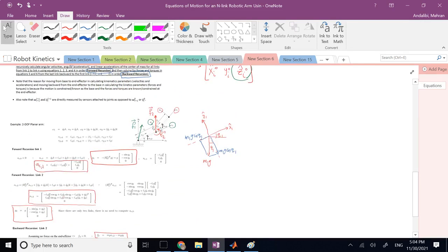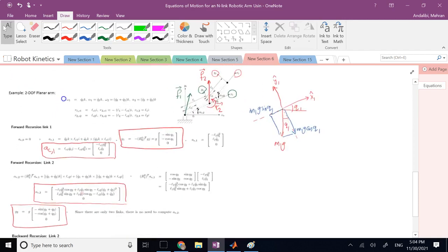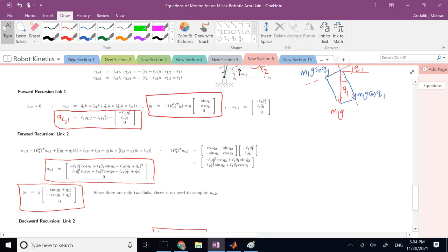So now imagine if your robot has 6 joints or something, how much more scary looking and much more complicated the shape of your dynamics equation is going to be. But as you clearly see here, the Newton method allows me to calculate F's that in the Lagrangian method, they disappear and they never show up.